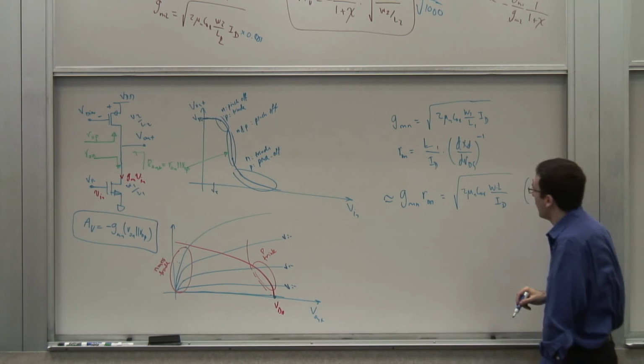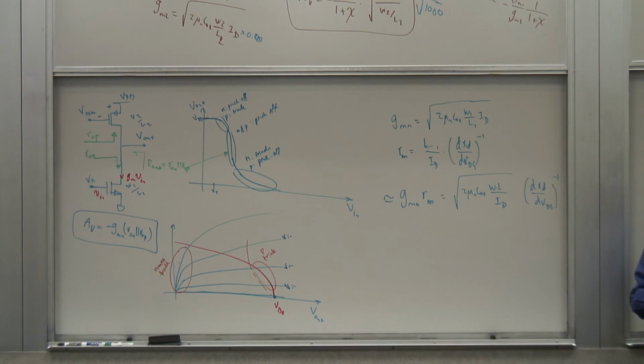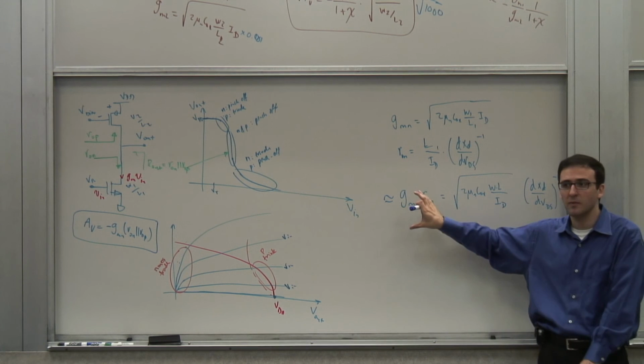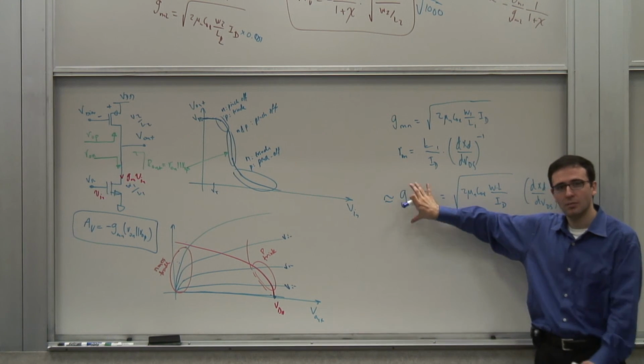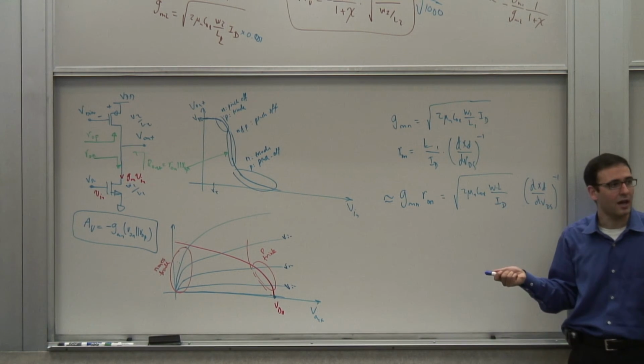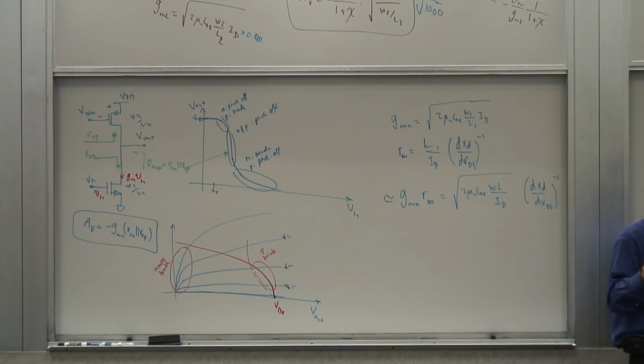So what do I need to do to maximize my maximum achievable gain? Right? This is the maximum achievable gain for given Gm and RO. But then, if I'm designing something, I can play with some of these parameters, and I want to know how I can maximize the gain. You can increase the dimensions of the device. Right, exactly. This is interesting because both W and L, increasing the width and the length of the device, will improve your gain, increase your gain.